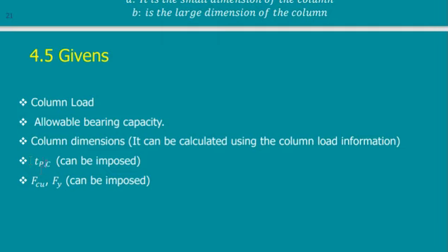Then I assume things. I assume the thickness of the plain concrete. Am I going to use plain concrete in my structural design or not? Will I use just 10 or 15 centimeters, in Arabic we say فرشة نظافة?